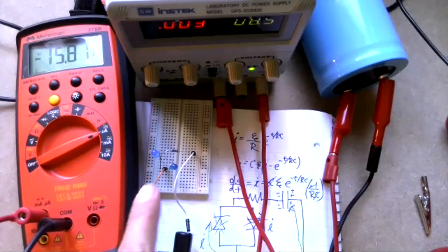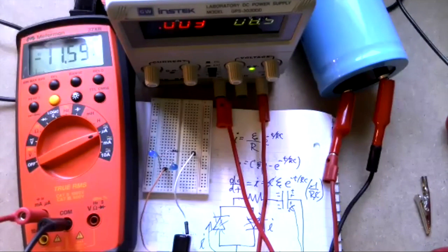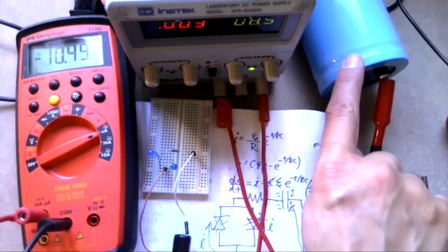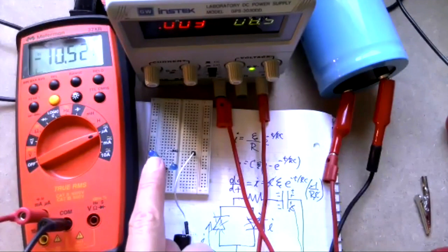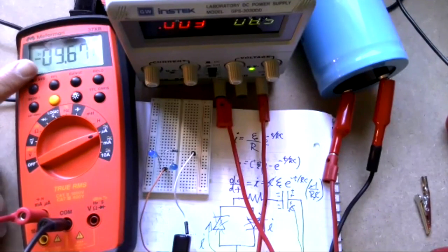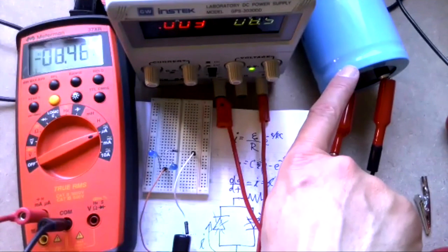If you'll notice, the LED has gone out here, and we'll talk about why. That's because you need enough current in your diode. And if the potential difference between my power supply here and my capacitor is not big enough, then this thing is not going to go on. And I should have been timing this, but I did not. This is taking a while here to charge up my capacitor. We're going on a couple seconds. That's because this is a pretty big capacitor over here.